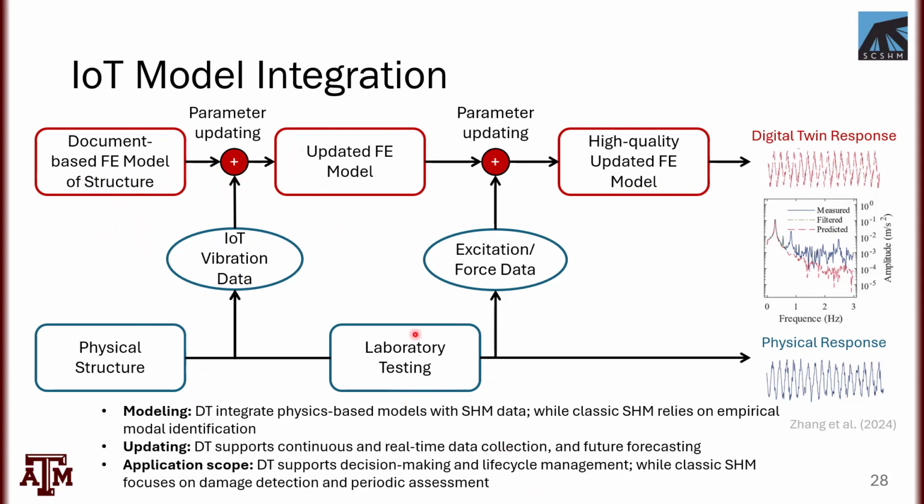If we are also lucky enough to be doing laboratory testing, then we have access to force data, excitation data, any sort of input that's coming in. We use those to get an even higher quality and updated finite element model. And then once you have your digital twin, you can simulate the digital twin's response in parallel with the physical twin's response. And you're now blessed with a tool that's giving you a continuous stream of forecasting, decision-making capabilities.